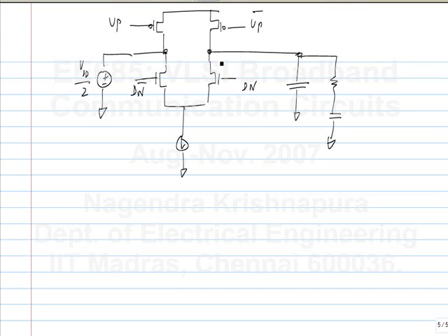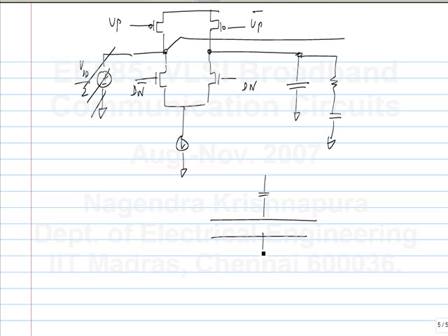Yeah, I mean that would be better actually, but generally it is hard to arrange that. Okay. So in that case you can not connect this to the fixed voltage, but have a differential loop filter. I mean differential loop filter meaning you just take it and replicate the loop filter, that's all. So now if you do have a VCO with a differential control, this is what you do.